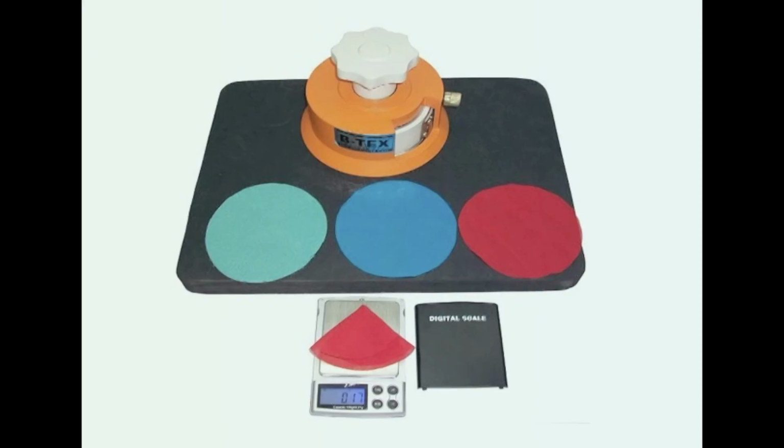Thus, today we have seen that the geometric properties of the fabric are very important, and by accurately testing all these geometrical properties, we will be able to predict the properties of the fabric, how it is going to be performing for a particular end use. So, in testing, accuracy has to be followed, and it is always better if you take a sample that is cut to correct measurements, and also it should be conditioned in a standard atmosphere.